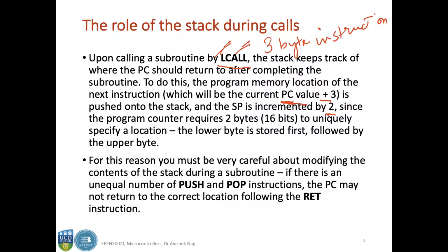Since the stack is last in first out, the lower byte is stored first, followed by the upper byte, so it will read the upper byte first and then the lower byte, and together they form the 16-bit address, which is the program counter value plus 3, and it will return to that line of the original code. For this reason, you must be very careful about modifying the contents of the stack during a subroutine.